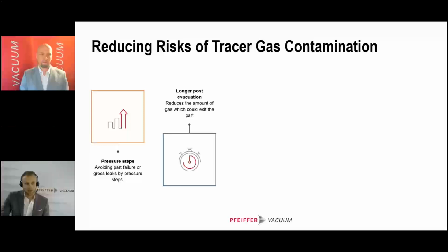Another thing that you can do is the so-called post-evacuation. So the longer you evacuate your test object after the actual test is done, the less gas, of course, stays in there, and the lower the chance is that you contaminate your chamber and your test object.